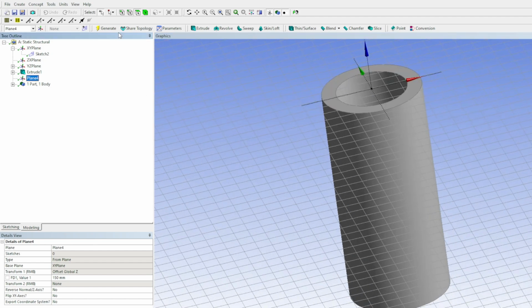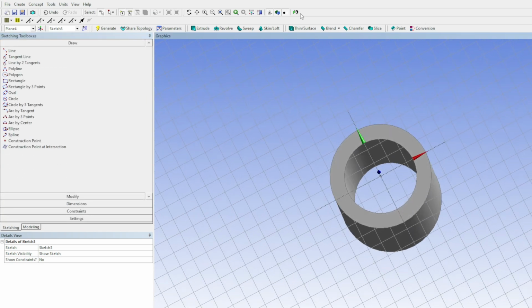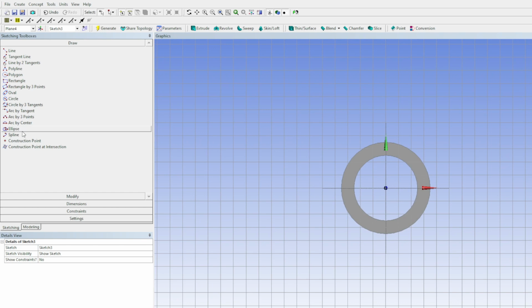So I'm just going to do the two end pieces first. I did have to do them separately because when I tried to mirror them, it was not too happy with it. So from here, we're going to go ahead and click New Sketch. Go over to the Sketch section, push this button up here to align to the plane.